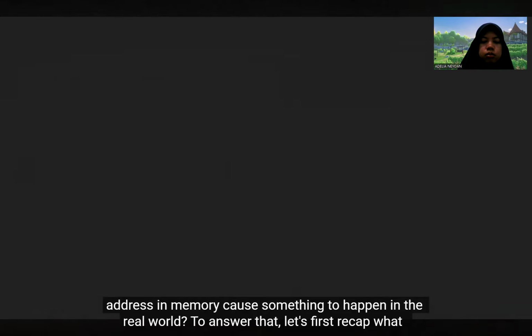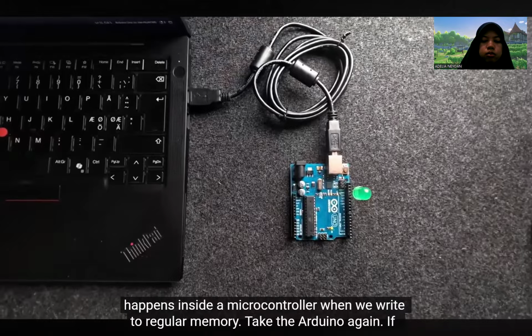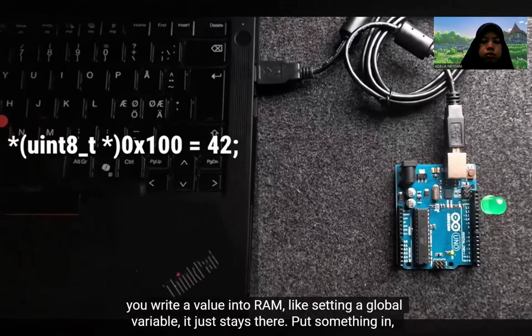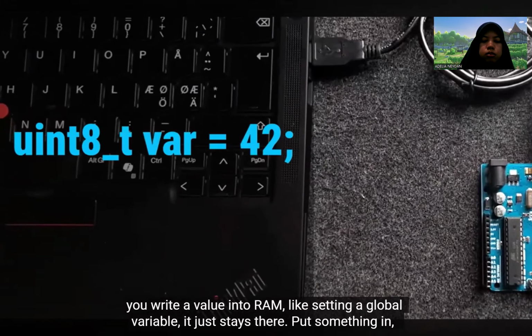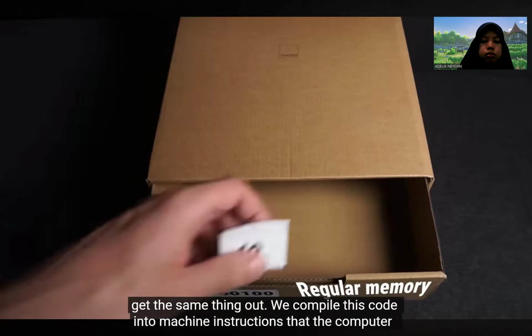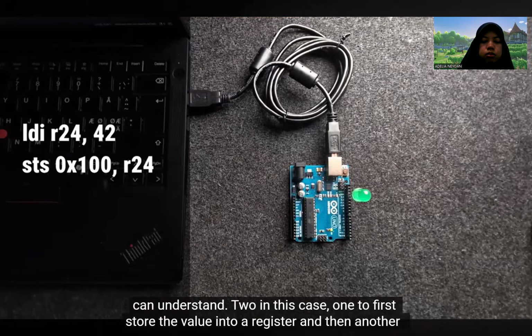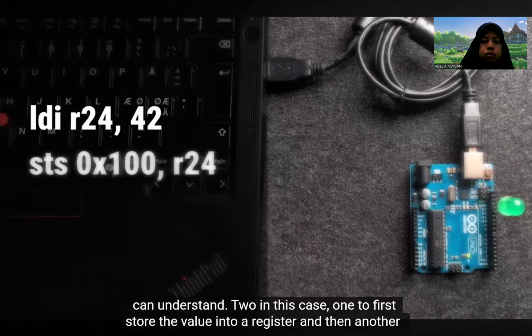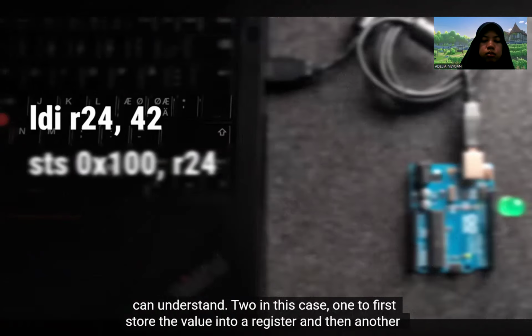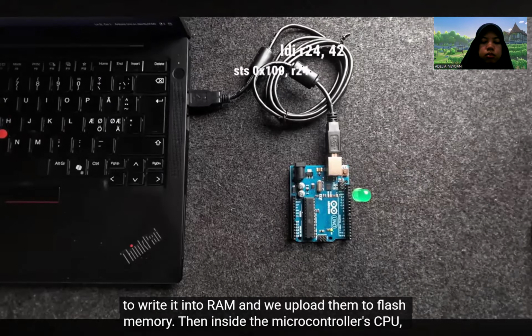To answer that, let's first recap what happens inside a microcontroller when we write to regular memory. Take the Arduino again. If you write a value to RAM, like setting a global variable, it just stays there. Put something in, get the same thing out. We compile this code into machine instructions that the computer can understand. Two in this case. One to first store the value into a register, and then another to write it into RAM. And we upload them to flash memory.